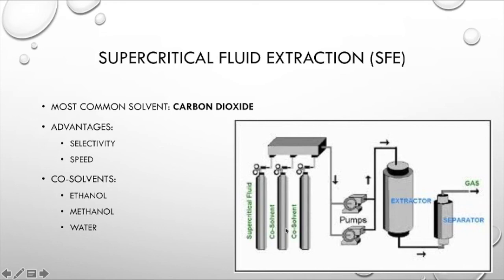As can be seen, the supercritical fluid is mixed along with the co-solvents or pumped into the extractor tank. And then after it is sent to a separator where further purification is performed. Sometimes a heat exchanger is included along here or before the extractor, just to ensure that the supercritical conditions are met within the fluid before the extraction occurs. As we'll see in the next few videos, this is not the only way to set up an SFE, but merely acts as a guideline for more advanced separations in more processes that are found in industry and in the cool applications that we'll see.